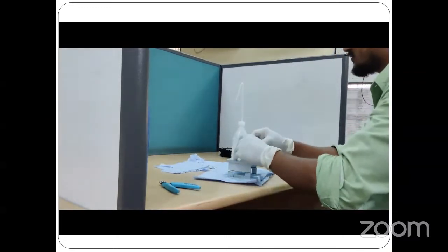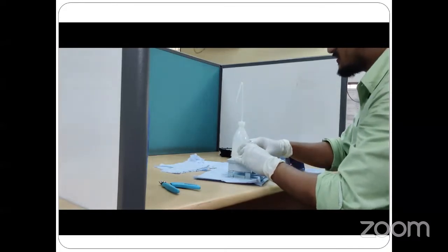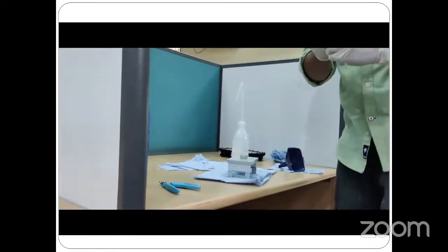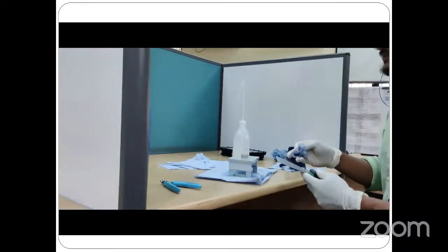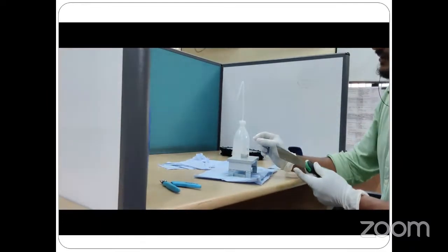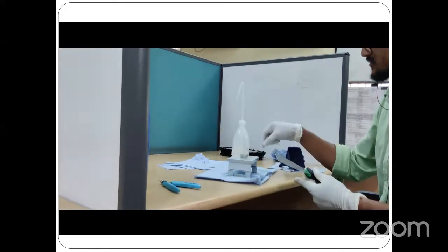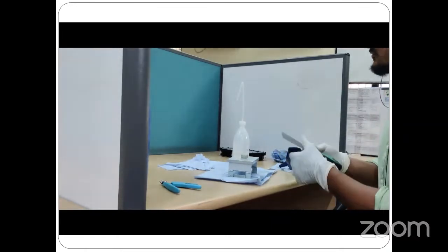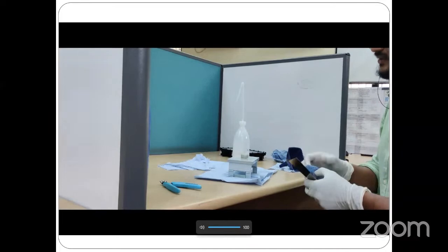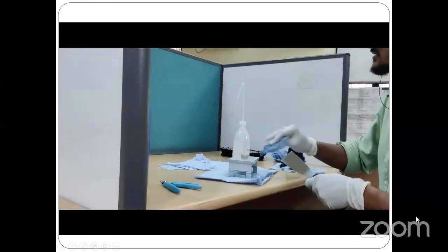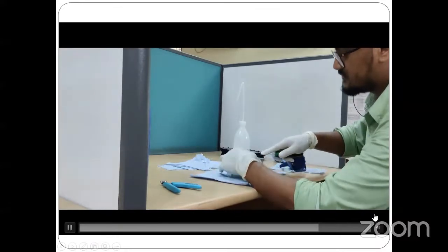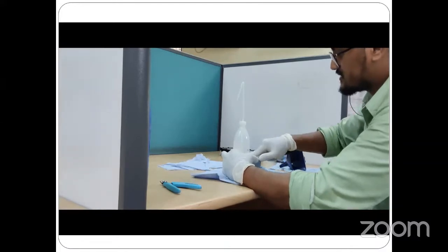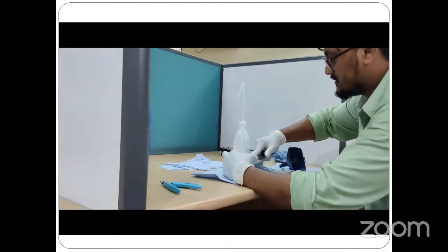It has solidified. Now we have to use the metallic one, so I'll bring that. Since the part has a lot of thickness, this plastic one is unable to slice it. So we will use this metallic one, but we have to be very careful with this because it may cause scratches on this bed plate, or it may damage the part. Gently we can break the support structure, but we cannot break the part. So we'll do it very gently.